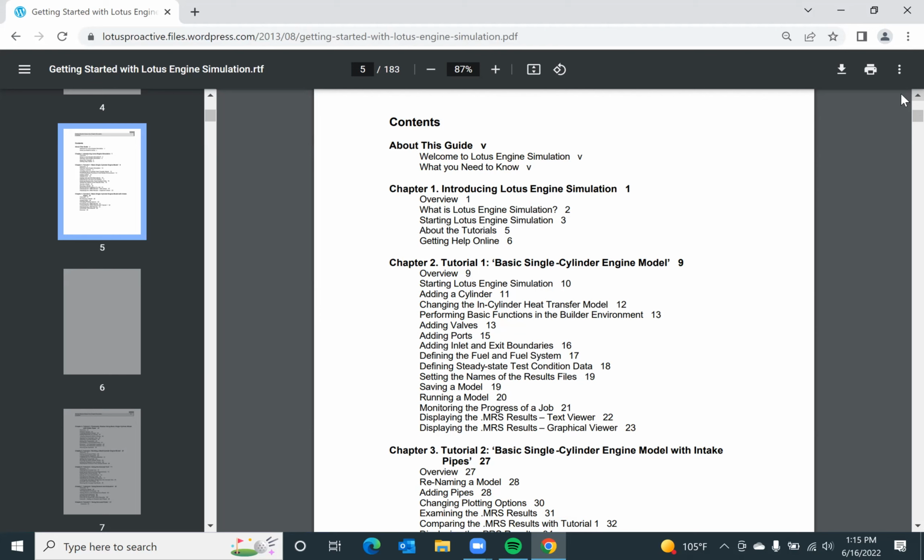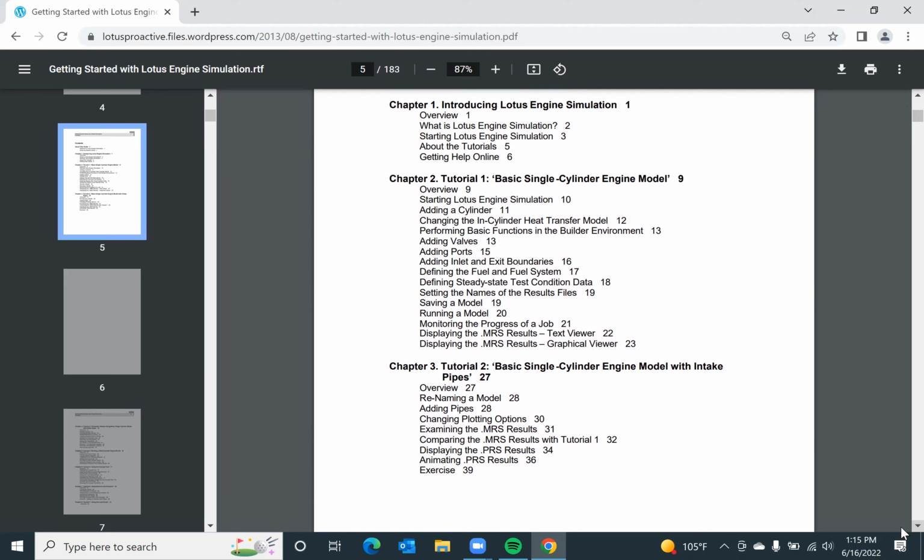Engine is not an isolated system. So what you need is a fuel tank, a fuel pump, you need to regulate the pressure, you need to maintain the inlet pressure, all that stuff. So if you want to include the effects of piping, effects of fuel delivery, effects of different types of mufflers, different types of sound suppression systems, single exhaust, multi-exhaust, deflected exhaust, all that stuff, they matter. They affect the performance of the engine. So you can add those pipe models that will tell you, if you bend this exhaust at this particular angle, what would happen to engine performance?